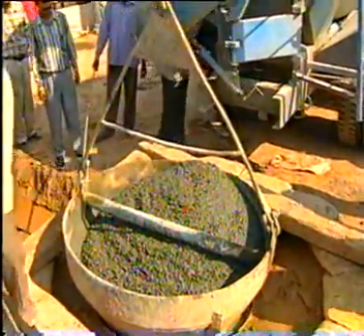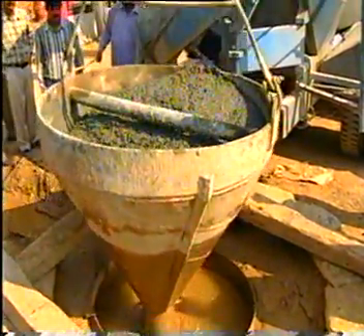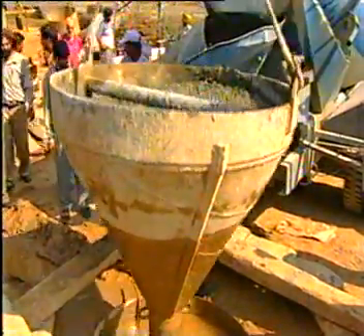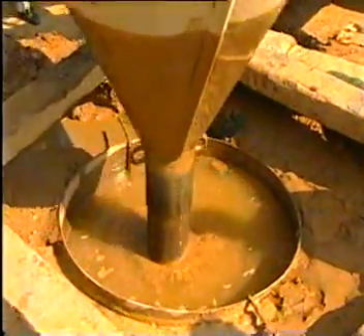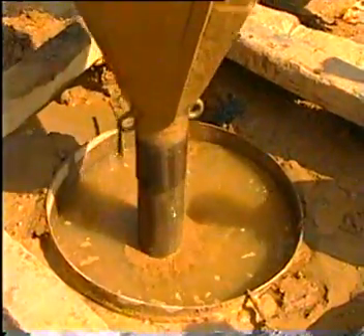After one batch has been poured, the tremie pipe is lifted up and down to allow the flow of concrete in the pipe. The bottom position of the tremie pipe should always remain embedded in the concrete in order to maintain a continuous concrete surface.